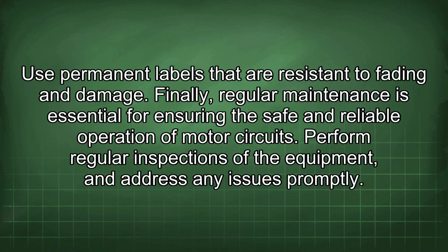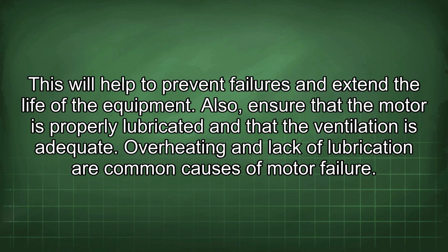Finally, regular maintenance is essential for ensuring the safe and reliable operation of motor circuits. Perform regular inspections of the equipment and address any issues promptly. This will help to prevent failures and extend the life of the equipment. Also, ensure that the motor is properly lubricated and that the ventilation is adequate. Overheating and lack of lubrication are common causes of motor failure.